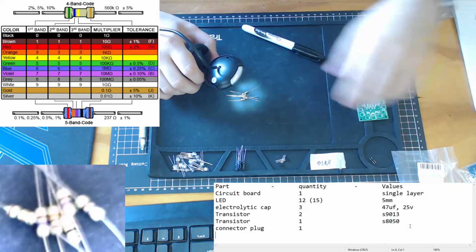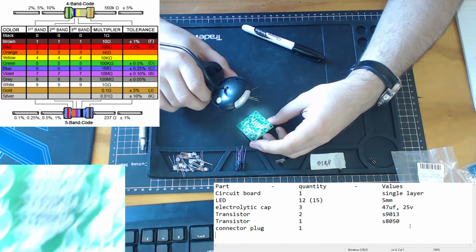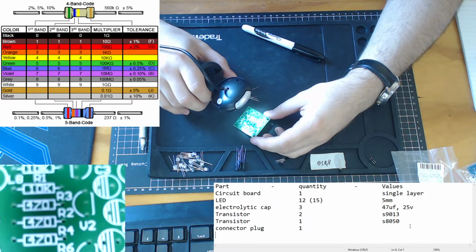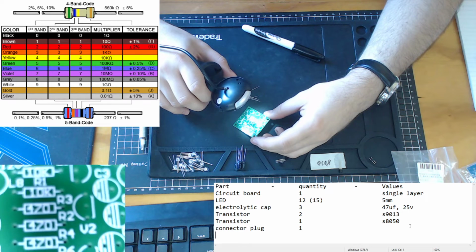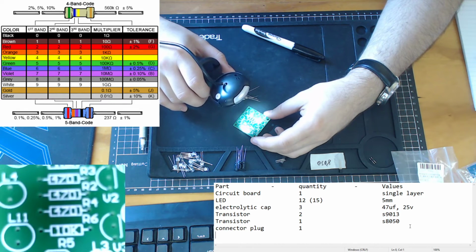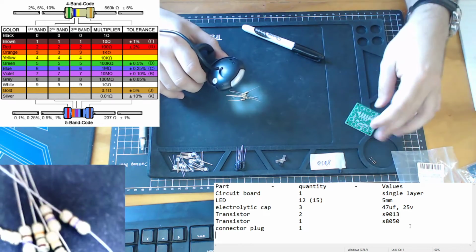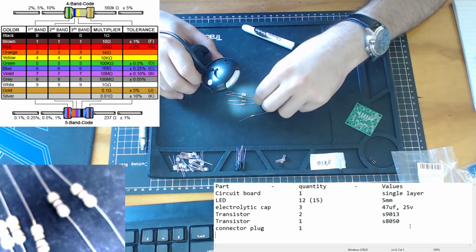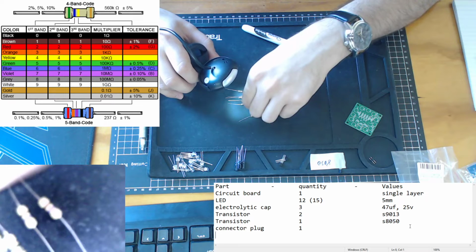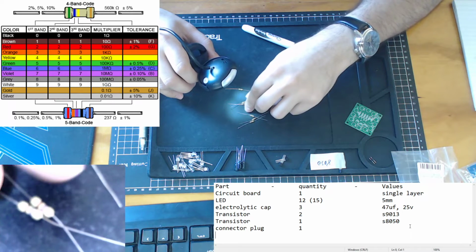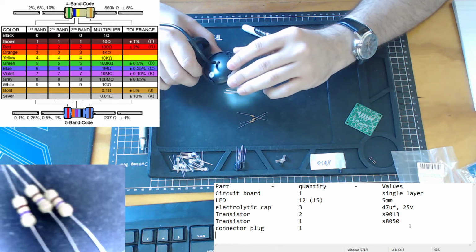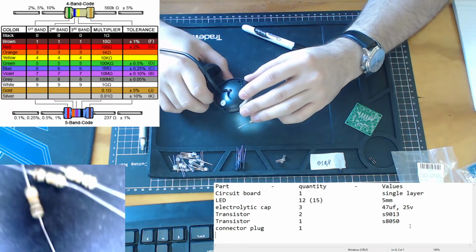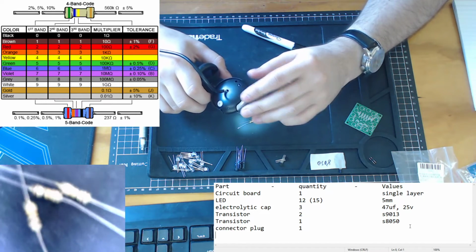Now if we look at our circuit, we see we have 10Ks and 10Ks and 470. We have 6 resistors in total, which makes sense in our circuit. Now we also know our circuit is divided up into 3 10K resistors, 3 10K resistors and 3 470 resistors. When we look at our resistors, we already know that there's color bandings on them, so I'm just going to group them. I'm grouping the 3 with purple, and the 3 with orange.